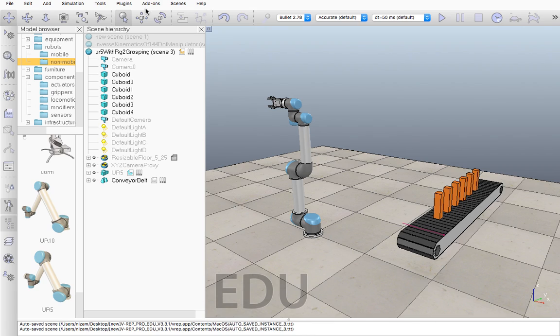So I suggest that you use SolidWorks URDF import. It's because all the revolute joints will be added automatically in the SolidWorks, but in the case of Blender, the revolute or prismatic joints are not seen. They are not automatically added in the Collada. You have to add them manually.